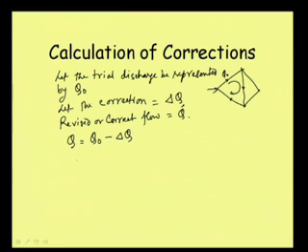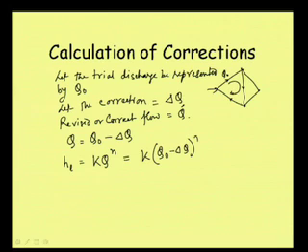Well, now what is head loss? Say head loss for the corrected flow is equal to K Q to the power n. Let us keep it in the form of Q to the power n first; later on we can make it 2. So, K Q to the power n, where n we are keeping as a general term. Well, this can be written as K times Q0 minus delta Q, to the power n.